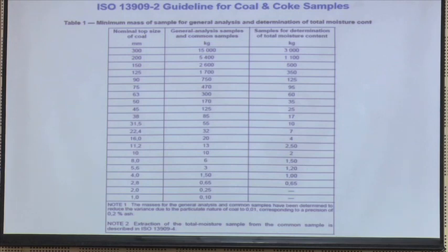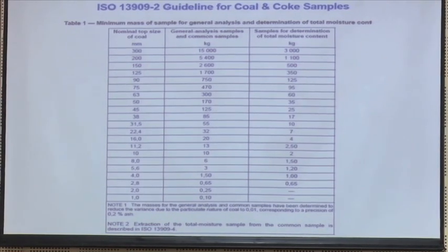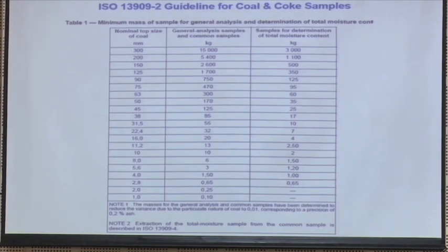So, what can I do? I have to put it into a container and put some nitrogen or some inert gas to make sure that it is not getting oxidized. If the surface characteristic is very important for you to decide which chemical I will be using for flotation purposes, this matters. If it is for ash analysis, it may not be that important, but again, what is the purpose of sampling, I must know. So, I have to take the precaution.